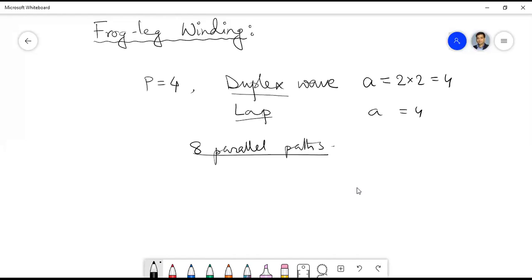That is called the dummy coil. Dummy coil means that it will not be connected with the actual armature winding. But you cannot leave any position on the armature slot blank, because that may create some mechanical imbalance. So to make up this mechanical balance, we generally place some dummy coil or dummy winding there.